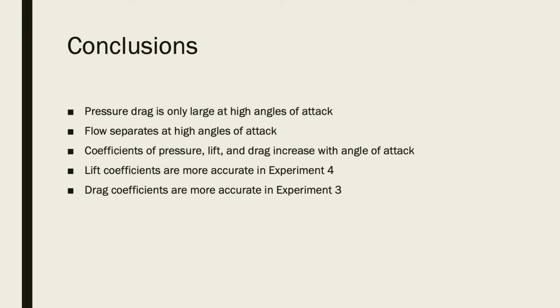Some major findings are that the pressure drag is only sizable at high angles of attack, such as 20 degrees. Also, the wake deficit rose markedly at high angles of attack, which confirms the predictions of flow separation and stall at an angle of attack of 20 degrees, which is beyond the roughly 15-degree stall limit. The coefficient of pressure, as well as the lift and drag coefficients, all increased as the angle of attack increased, as expected using the wake deficit method.